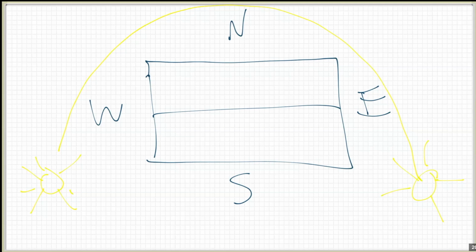I like to sort of simplify it a lot. It's all about your latitude. And if you're concerned about south-facing arrays, just remember that a south-facing array, which is facing away from the equator, in Melbourne is about as good as the best facing array in Germany. So if you're saying you can't put it on the south, then you shouldn't even install panels in Germany in any direction, because they don't have as much solar radiation over the whole day. So yes, south works, but it will work much poorer in winter, and in summer it will work fine. In fact, it'll make almost no difference in midsummer in northern latitudes of Australia because the sun's straight above you.